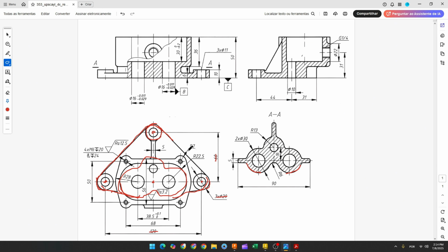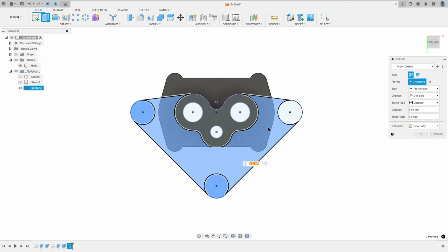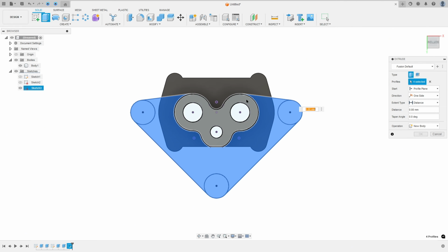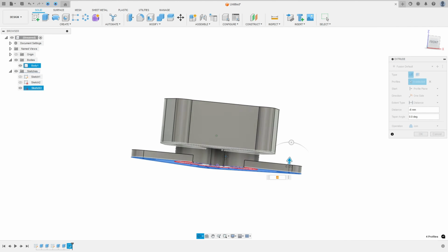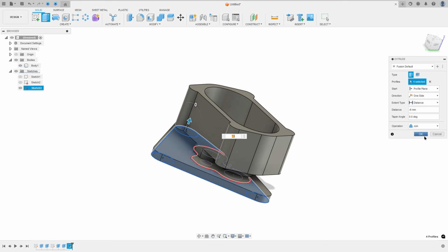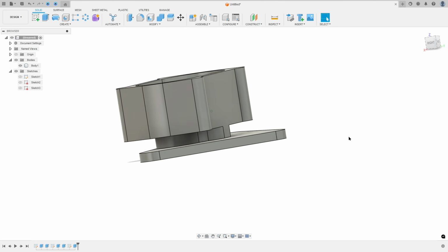And we need to extrude this area 6 millimeters, okay? This distance here. So finish the sketch and select this profile here. Go to extrude, sorry, select all this profile. You don't need to select this area here, only this. The distance here, 6 millimeters, minus 6 millimeters. Okay, we made this. Operation join, press OK. We made this, okay.